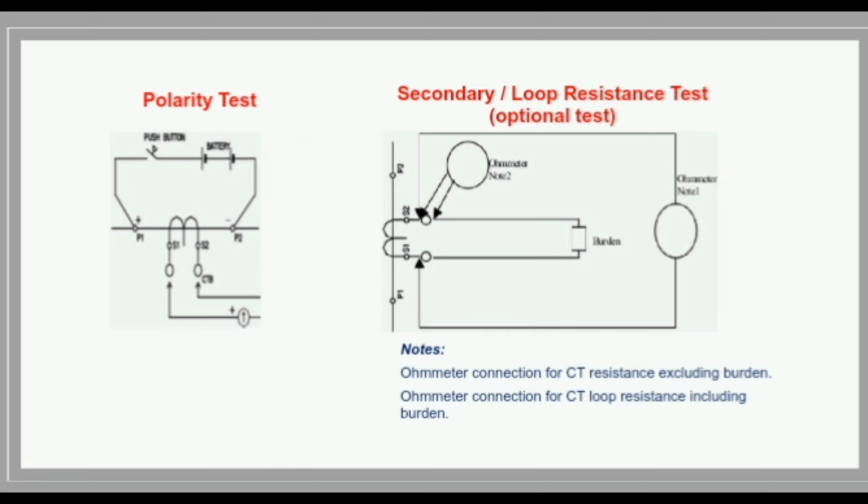The circuit connection shall be made for low resistance. Measure DC resistance including CT and load, phase by phase, so values can be compared between them. Okay?